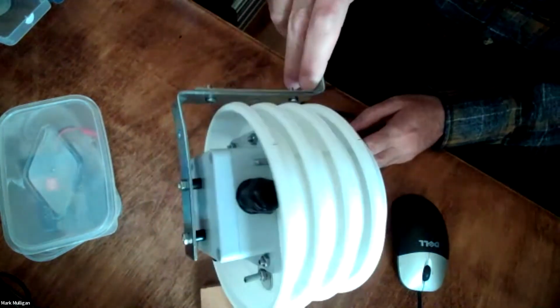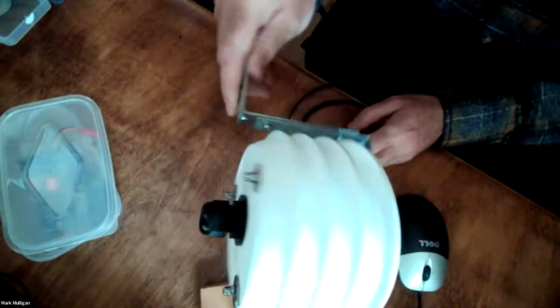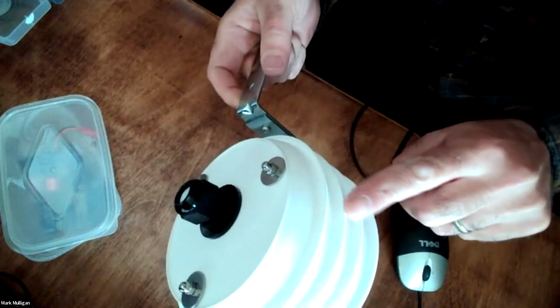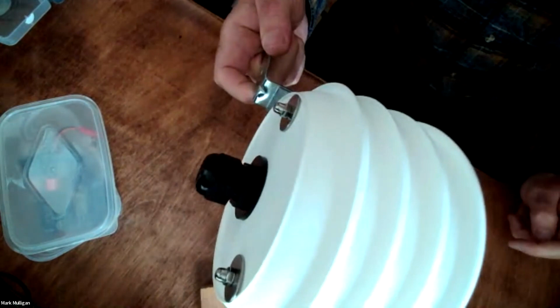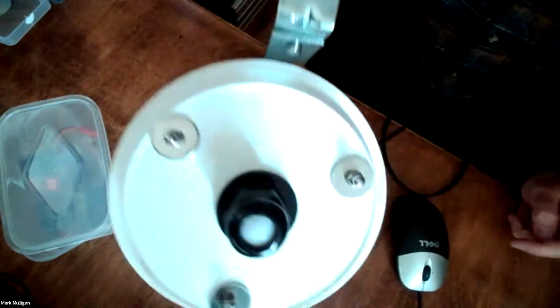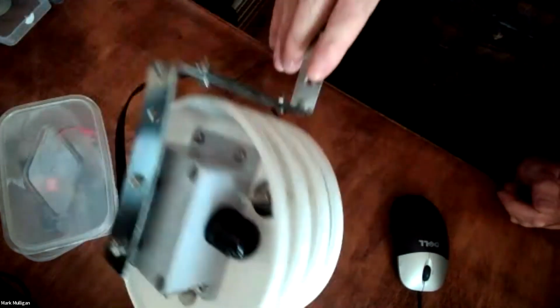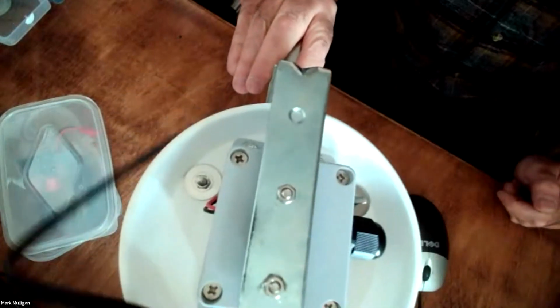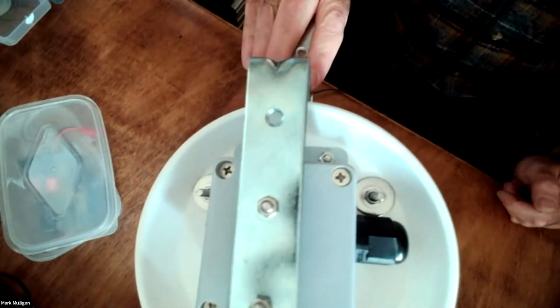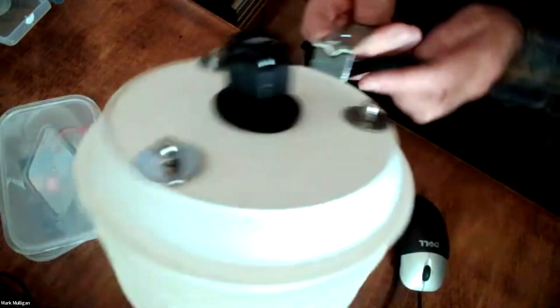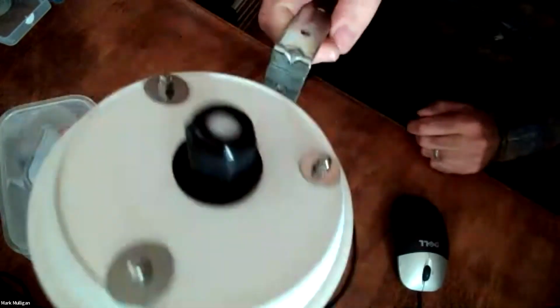is the latest version of our temperature, humidity, air pressure, solar radiation design. It uses, as you see, plant pot bases to create a Stevenson screen. It has a cheap solar radiation sensor on top, and it has the temperature sensor at the bottom, protected from heating by the sun. This would normally cost about £600. We can build this for about £16. Right. And that is, of course, an important component of a weather station, to be able to measure those variables.